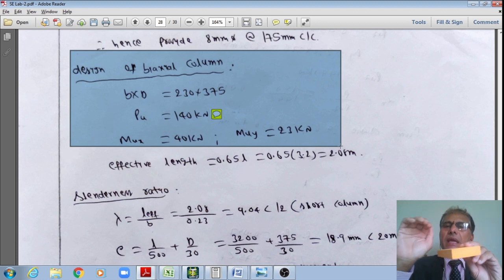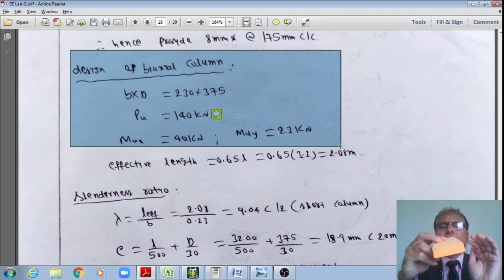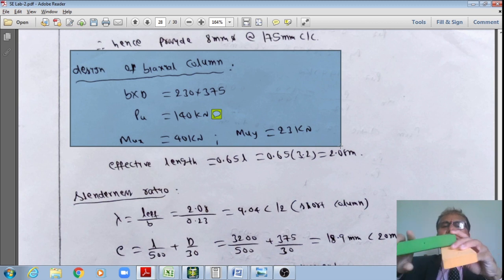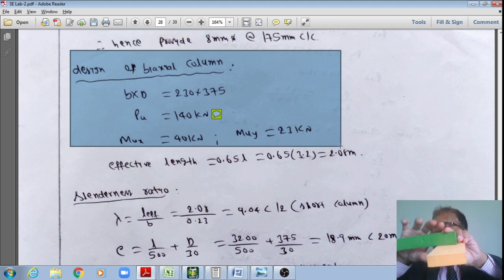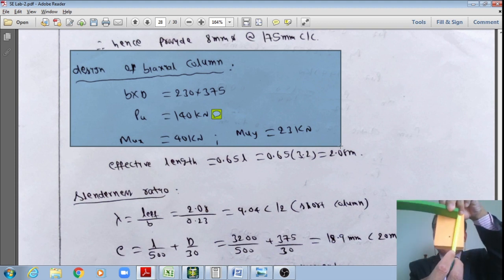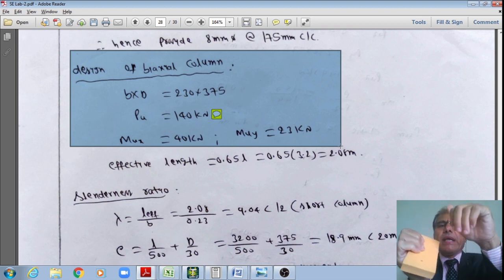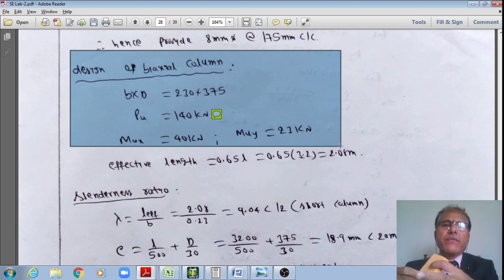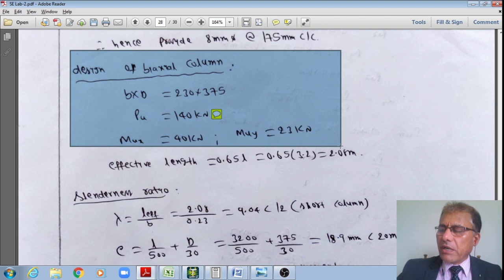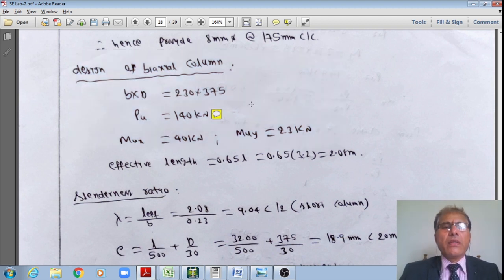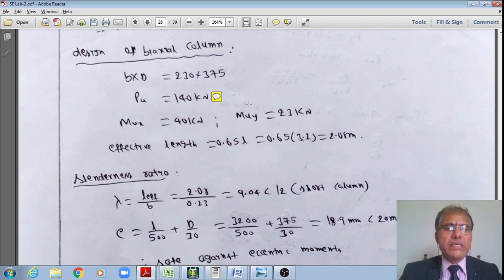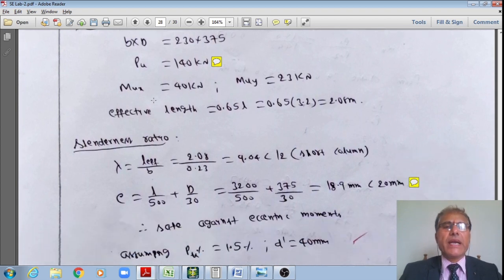Therefore that is how this bending moment is about one axis of this beam. This beam is acting in the x direction, if at all this is assumed as x direction, right? As well as from the transverse direction, right? 3-span continuous beam is applying the moment on this y-axis. Therefore that is how this column is subjected to biaxial bending, right? Therefore that is how this is critical compared to the previous column design, student, right? I hope you understand the manual designs. However, we'll compare this with STAAD later, right?